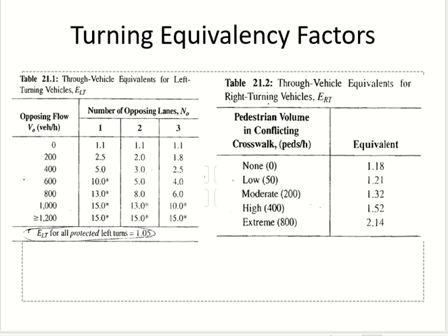What did you do in the LOS calculation to convert the heavy vehicles to passenger cars? What was the factor? Heavy vehicles factor. Okay. So we know one type of conversion. If you have heavy vehicles in this lane and this lane and this lane, we can convert all of them into passenger cars with the use of the heavy vehicles factor.